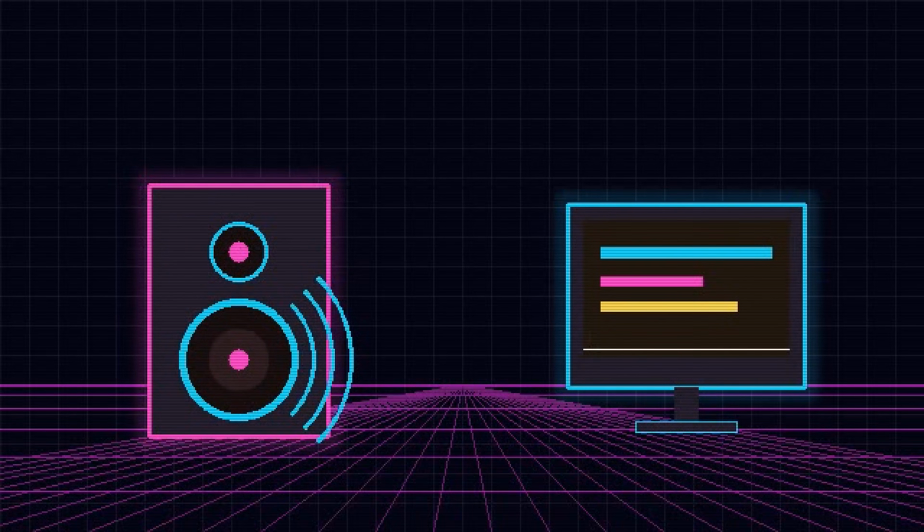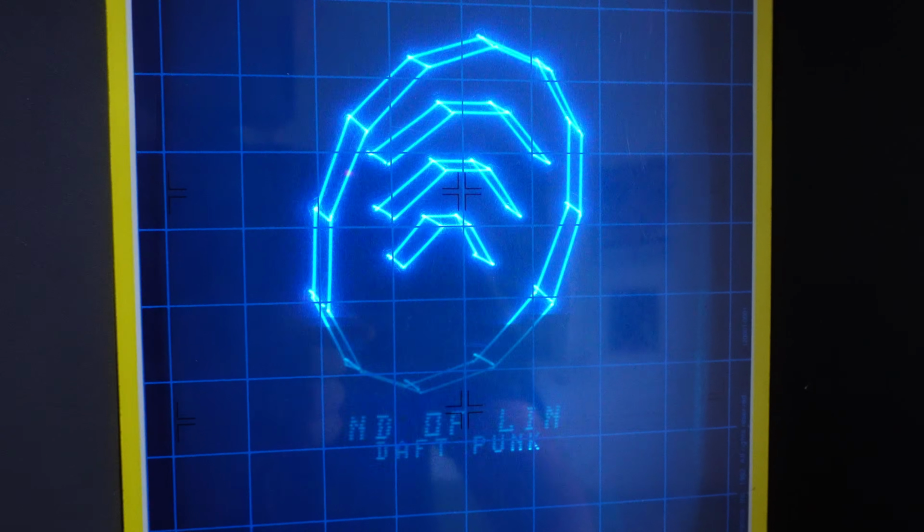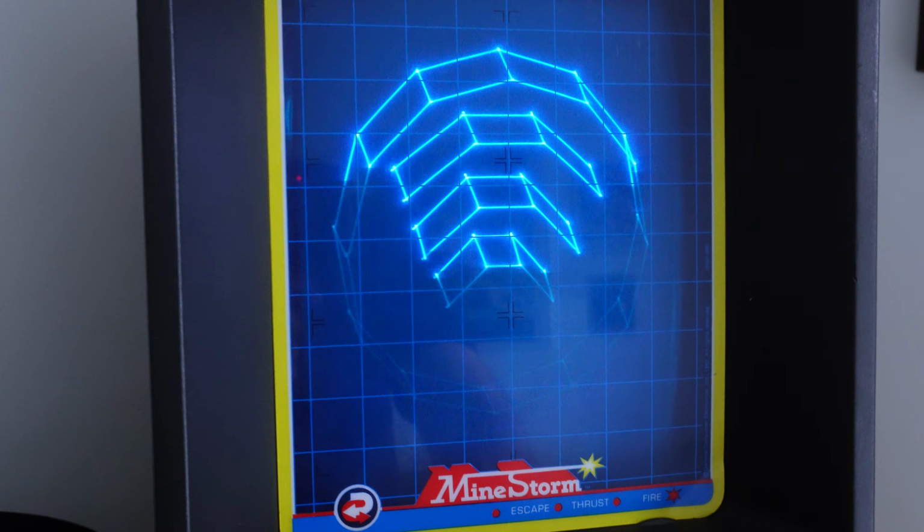Once the audio was stable, I still needed to use the display. Because sound and graphics cannot use the DAC simultaneously, the program alternates between them. Most of the time, the DAC produces audio. Around 25 times per second, the program briefly pauses the audio, gives the DAC to the display, draws the text and graphics, and then returns control to the speaker.